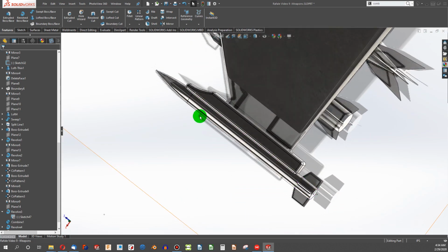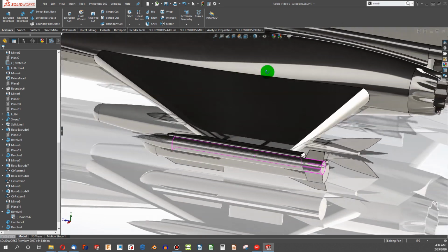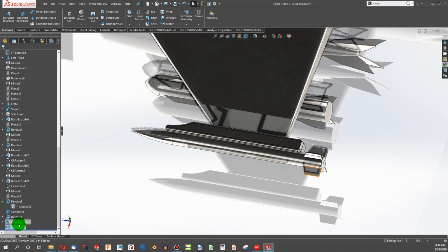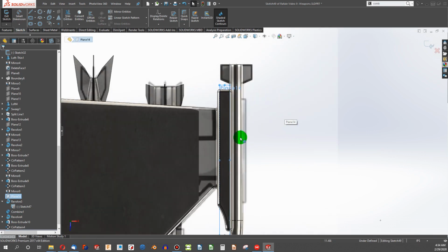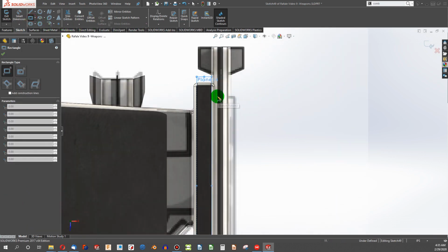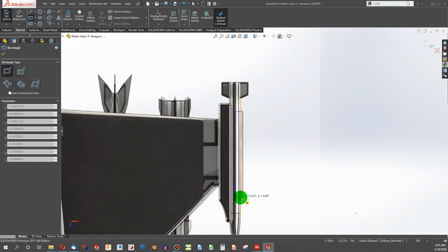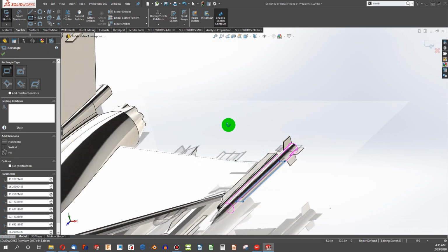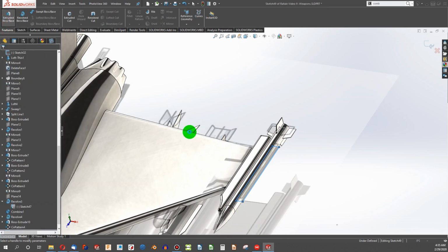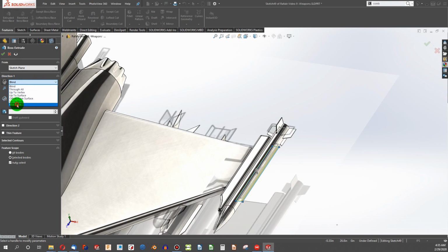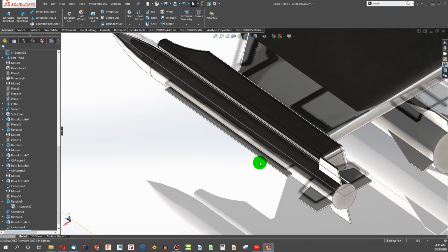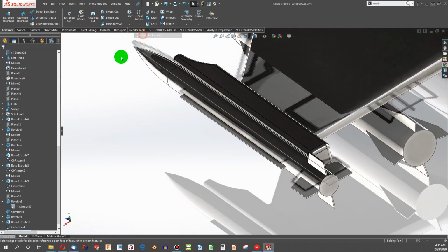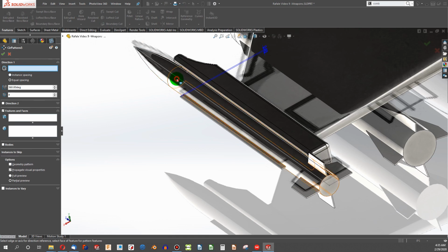The next thing you'll see, our missile has kind of a fin going down the side. So let's work on that. Again, with plane 14. I'm going to do a real basic rectangle, corner rectangle. Features, extrude, again 25 thou, mid-plane. There you have a little nice surface there. Let's do a pattern on that. Go a direction here.